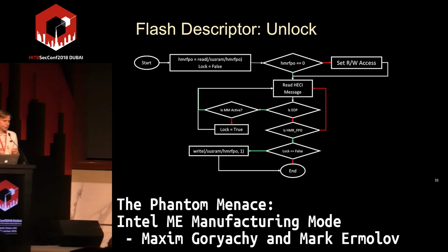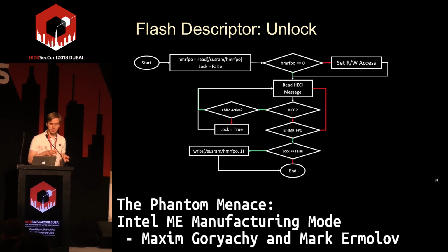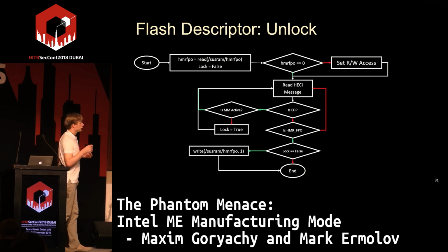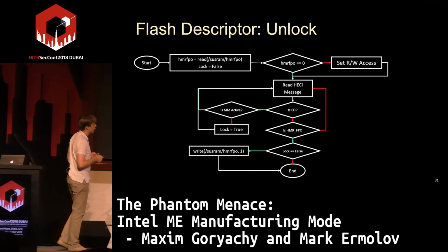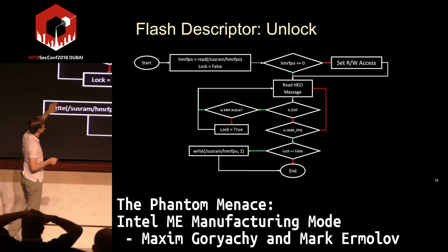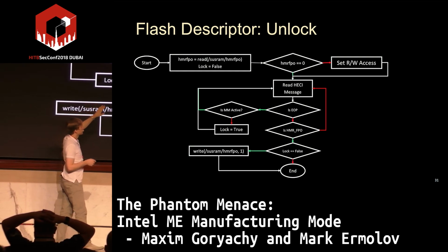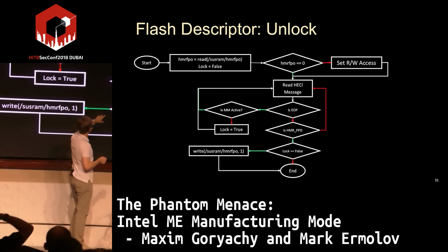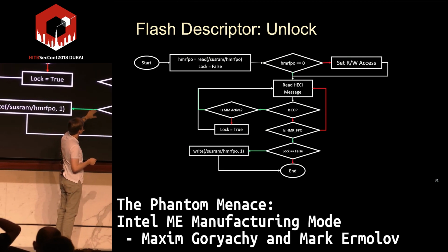And if this file contains 0, ME just reads HECI messages, and if it receives end of post, it locks the configuration, or waits for HMRFPO.